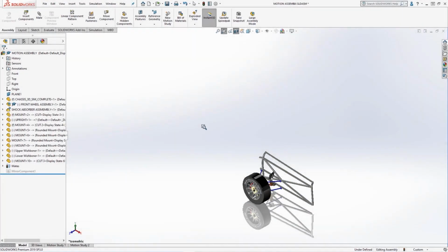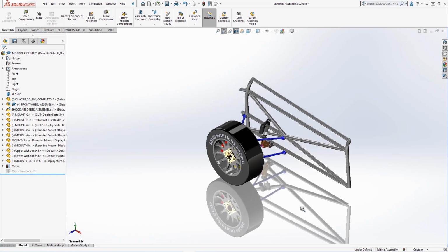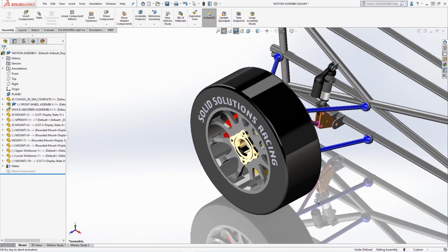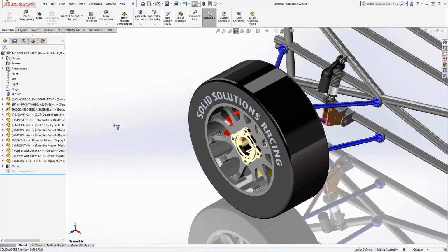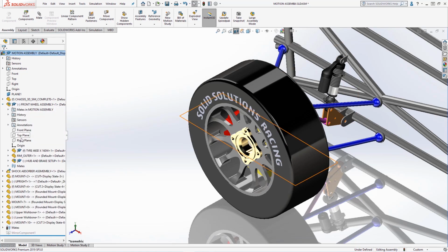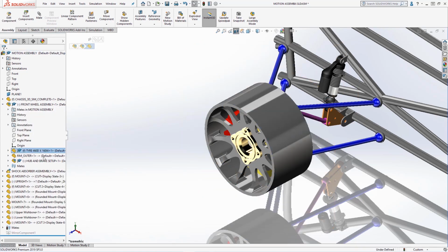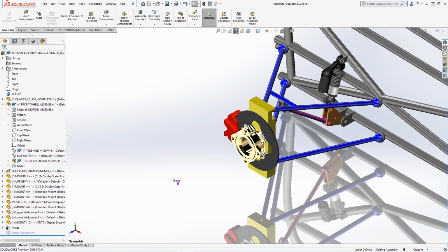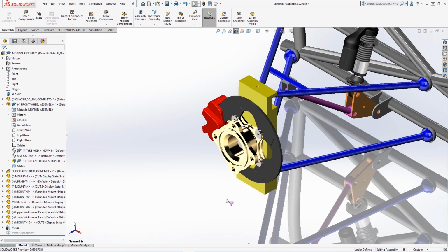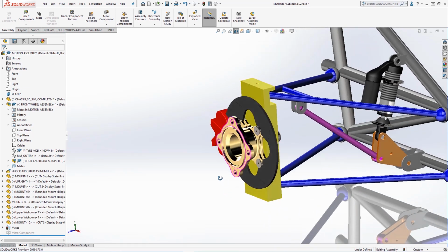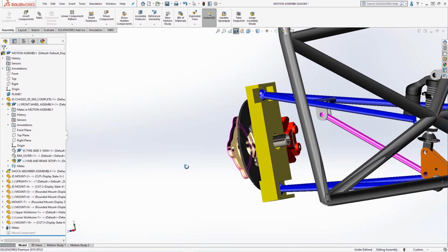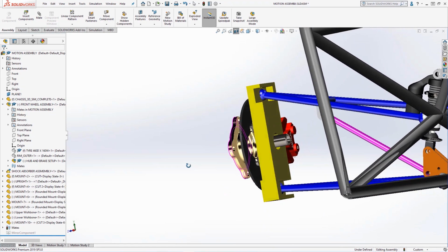In this analysis, we will isolate components to view just a subsection of the wheel assembly. Hiding both the tyre and rim, we see the brake assembly and wishbones connected to the knuckle upright body. This body is a simplified blank volume which we will analyse in greater detail, and it represents the design envelope and mounting points to base the optimization study on.